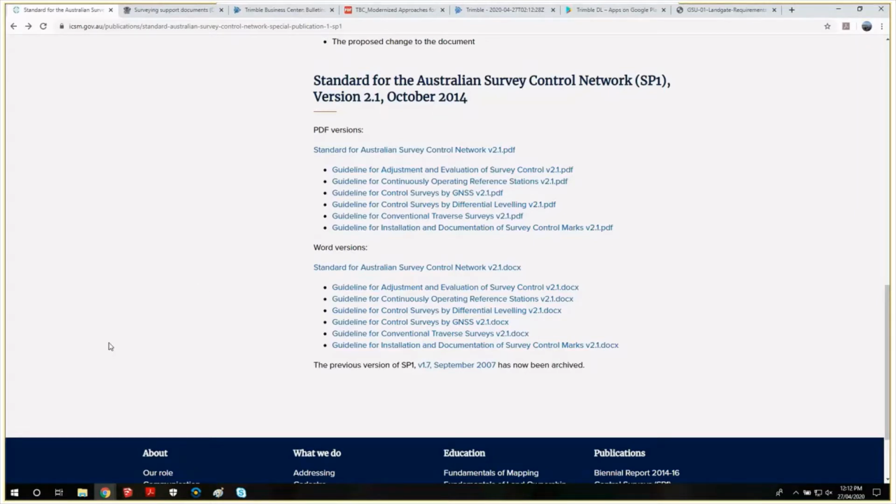Okay, so if you're looking for some information around GNSS static surveys for post-processing, like we're going to run through today, today's session will be around static, which are longer observation periods, rather than looking at something like PPK, where it's the equivalent of doing your normal rover survey, but you're actually doing quite short occupations on those points, or something where it's being logged as an actual trajectory and you get a little breadcrumb feed of the entire route that you've passed through.